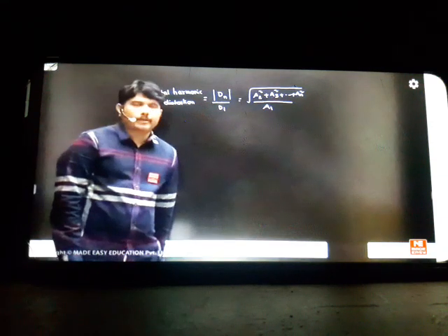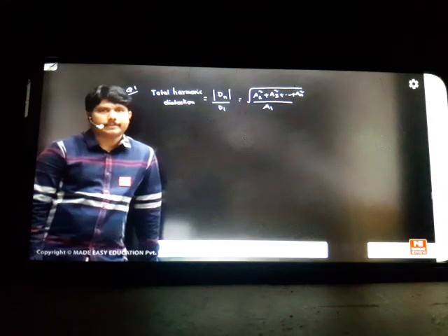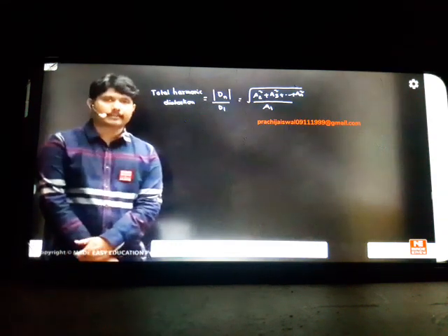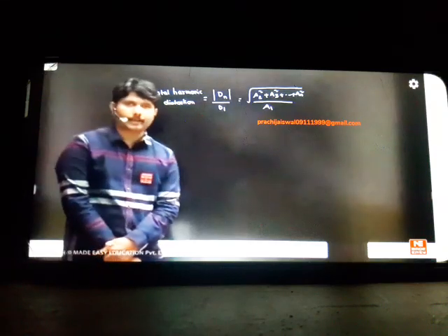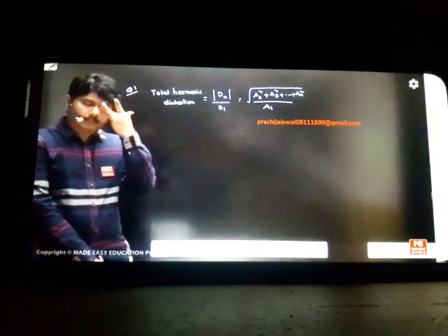So Parthasarathi, keep a point in mind: he is talking about HFE. He is not asking 1 plus HFE. Okay? HFE, if you ask, the formula is IC by IB. If you ask 1 plus HFE, which is called gamma, we can write gamma as IE by IB. If you get a little confused, the answer will go to 10200. Okay? The beta formula is IC by IB. Please remember that. It is not IE by IB. If you ask gamma, then you can say IE by IB. That point will confuse you actually. Okay? I hope you understood it.